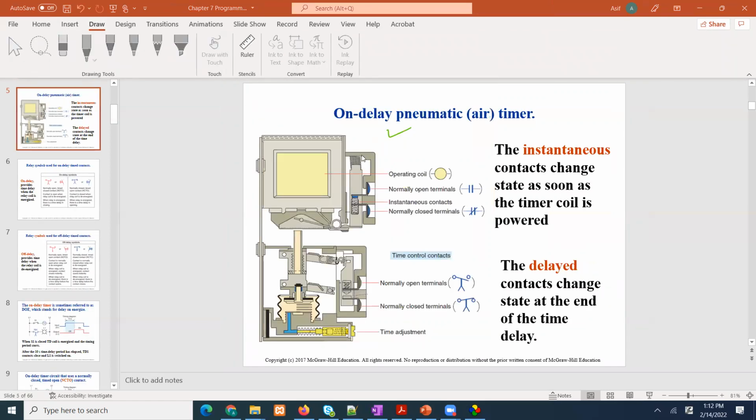You see, this is not different than what we talked about with the contactor. You guys remember? In the contactor, what did we have? We had a spring, yeah? And associated with this spring, we have normally open and normally closed contacts, yes? So when the spring is actuated, normally open is closed, normally closed is open, yes? Now similarly, this relay is used on a smaller voltage, and the contactor we were using on a larger voltage, yeah? And right here, it says the operating coil.